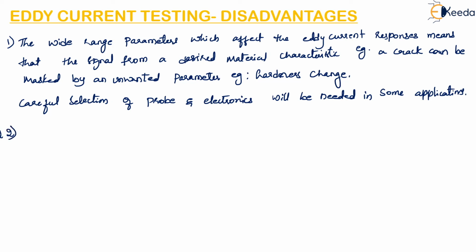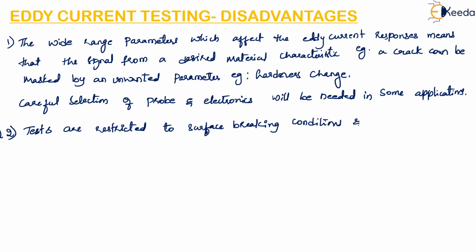So generally this test is restricted to surface breaking conditions and slightly subsurface flaws. So the deeper flaws which are present inside the component cannot be detected with the help of this method. Tests are restricted to surface breaking conditions and slightly subsurface flaws.